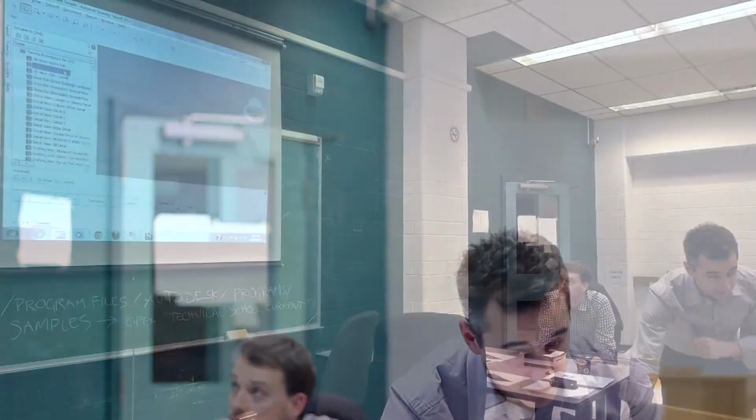It so happened that the last view saved was this one, but really I prefer a 3D view. So I can choose to export one view, which is my 3D view of the entire model, or I can export all the views in the model. Is it useful to export all the views? It is useful because as you select building components in your model, they'll be highlighted, and you can actually show the views and sheets that show that component. Again, it's not the subject of this presentation today, but keep in mind it is possible.